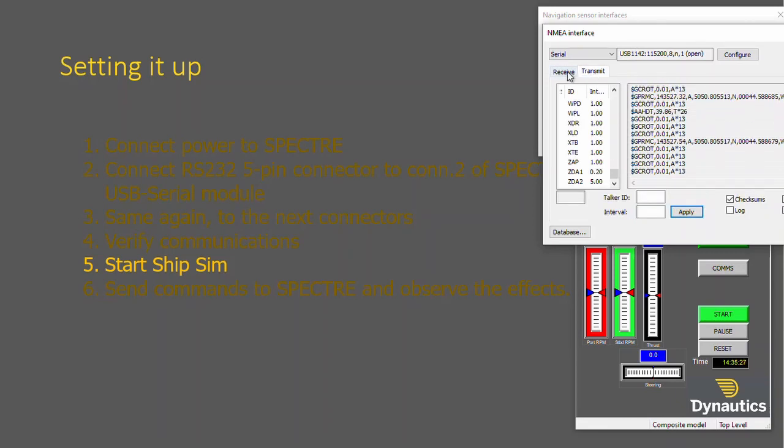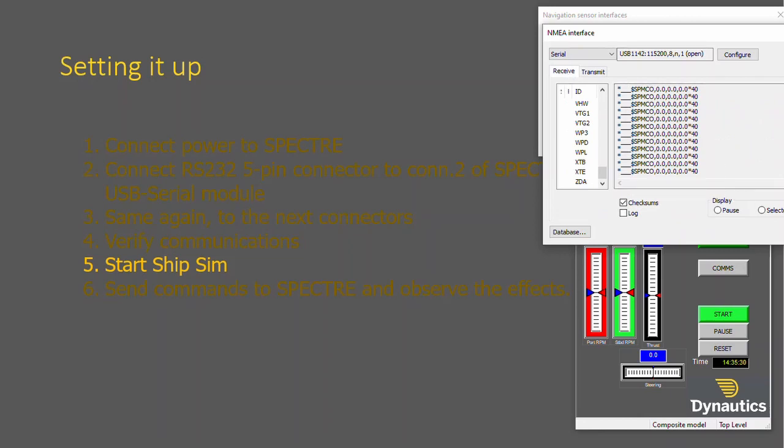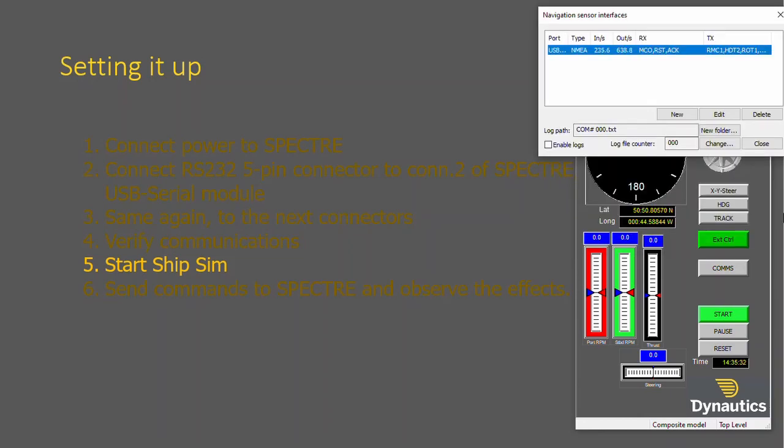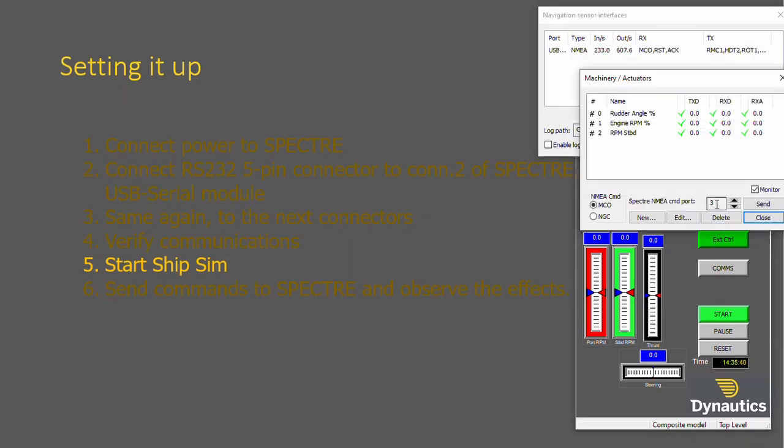It's unchanging. The other thing that can happen is that it's coming out of Spectre, but on the wrong Spectre port. So if you right click on this external control button, that port there specifies which Spectre port it's supposed to come out on.